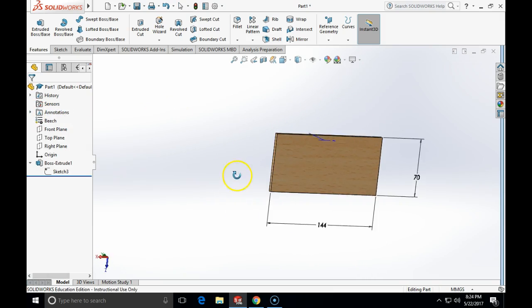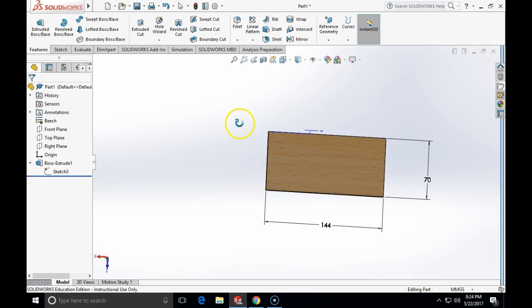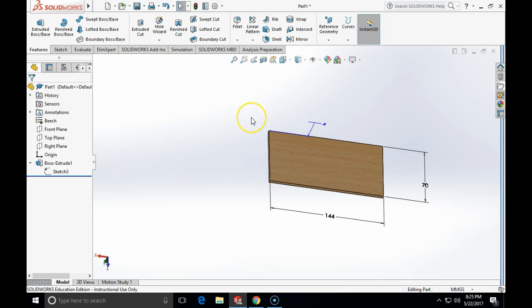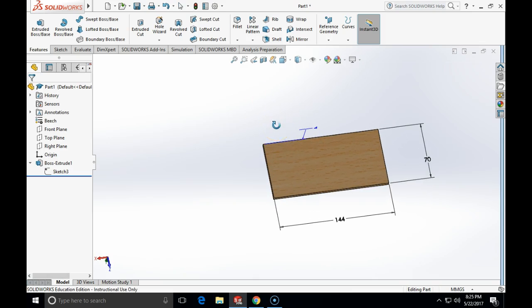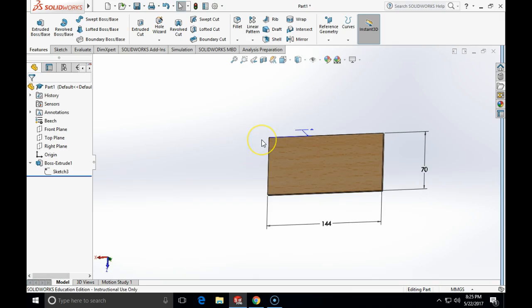Now, let's put those two recesses into which we are going to place the goal part itself. So, if we look into those recesses, it will be just the two rectangles. However, they are symmetric, so we will see now our first placed features. And the first placed feature that I will show you will be the same as extrude, however, this time it will be an extrude cut. What means we will cut through the object.